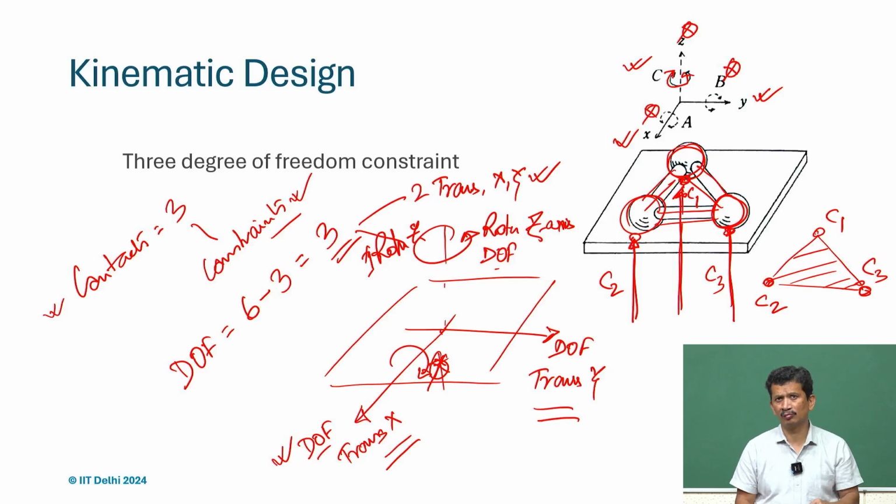That is why we talk about 3 contacts, a 3-legged chair, a 3-legged table. The moment we have 4, we have trouble. How to make that contact? I can put another ball, but then I have to make that C 4 point lie on the same plane, which means added constraints or added tolerances on the component, which means higher cost.